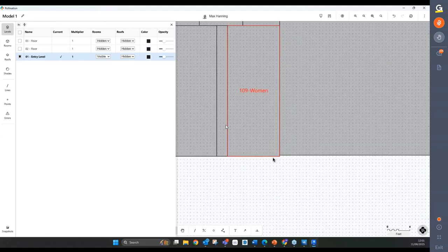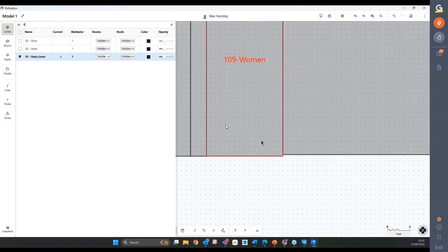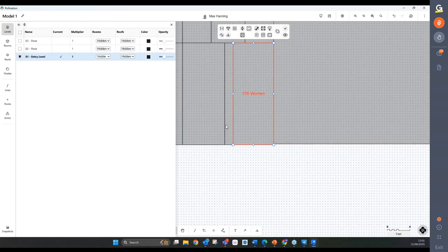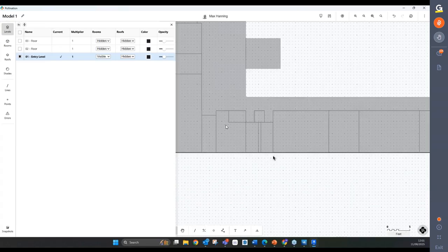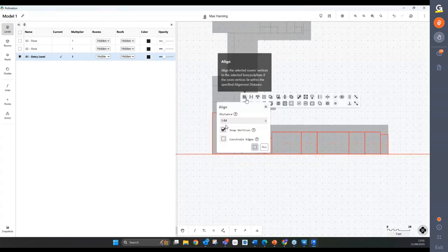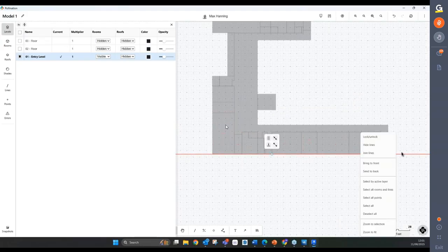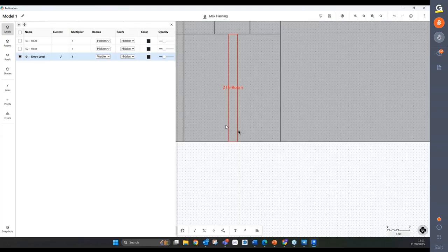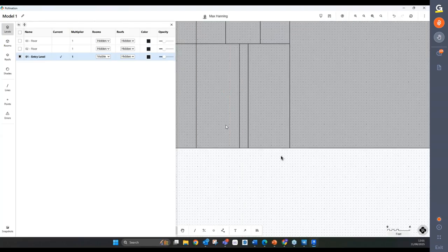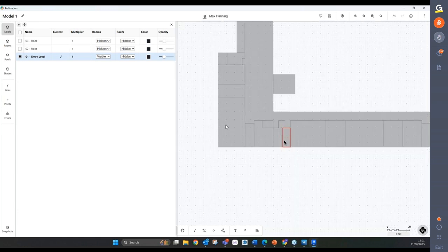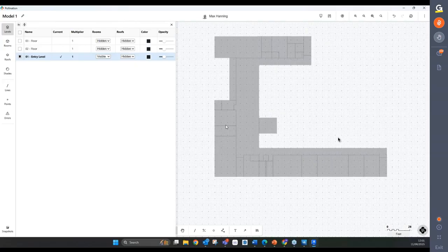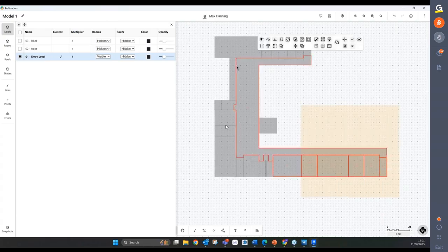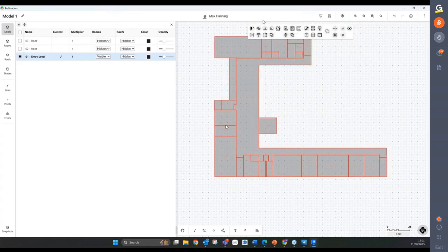And then another really useful tool, without wanting to go through all of the tools available, would be the alignment tool here. So there was a slight misalignment due to different wall thicknesses in our Revit model, so everything can just be realigned to the same alignment line there. And that can help resolve things like room overlaps and general misalignment geometry issues that you might notice. But just conscious of time, I won't go through the entirety of the model editing tools that are available, but more or less any change and correction you would have to perform to your geometry can be done within the model editor.